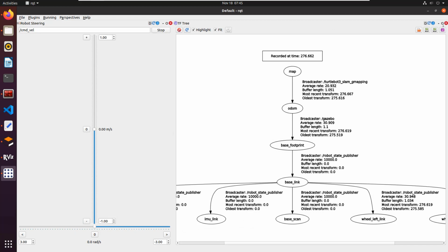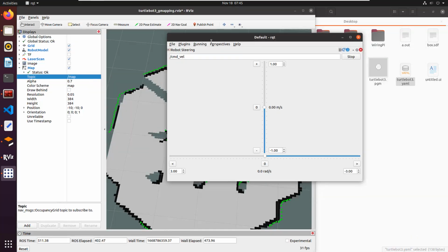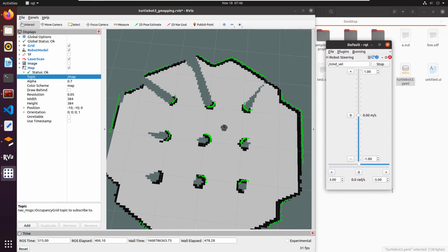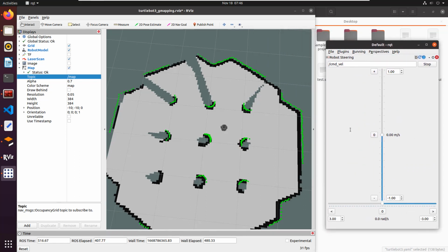The map is not finished now, so what you can do is simply finish the map by manually moving the robot, or in the last class I mentioned the exploratory algorithms, right? So if you run the exploratory algorithm, the robot will automatically go through these places and create the map. Okay, so the exploratory algorithm will also work, but here we will get some control. It's a manual movement, right? Yeah, so simply move the robot.